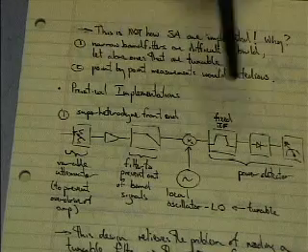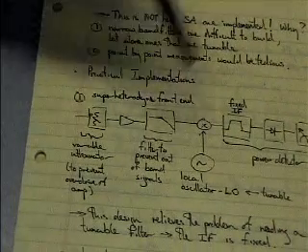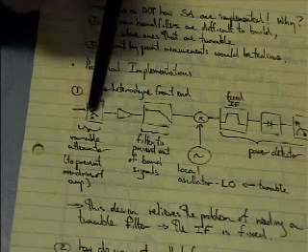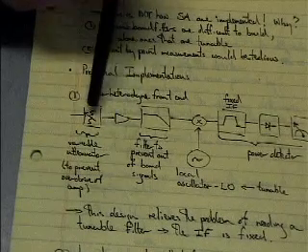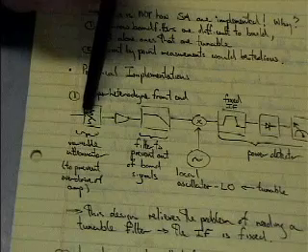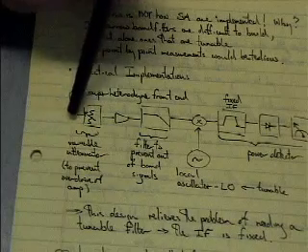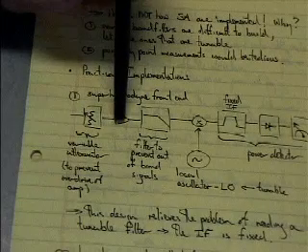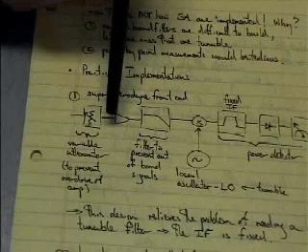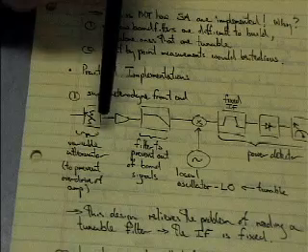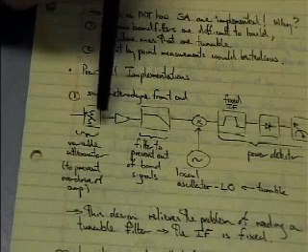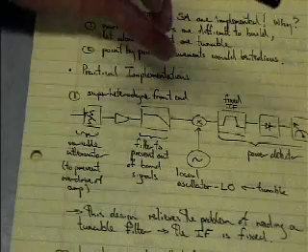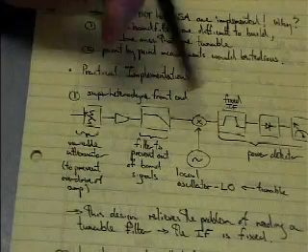Okay, so a couple other things that we have that's of interest here is that at the front end, we note we have an attenuator here and an amplifier. Well, the reason why we have an attenuator here is so that we can basically pad down or knock down our signal so it doesn't overdrive this amplifier. As we know, practical amplifiers are only linear over a certain range. If I drive this thing too hard, it's going to be nonlinear. Nonlinearities introduce harmonics, etc., etc.